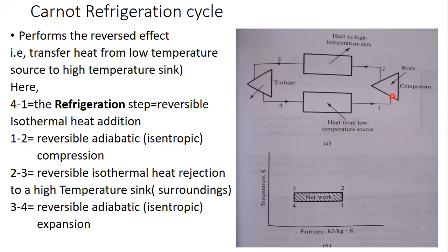Then that working fluid has very low energy. It has to reject the heat to our surroundings, which is at a higher temperature. So this working fluid needs more energy than it presently has at the freezer compartment. So we will be doing work, or energizing, or pressurizing, or applying some additional energy to that working fluid by means of a compressor. Thermodynamically, compressor is a term denoting where we are supplying external work or energy to a system.